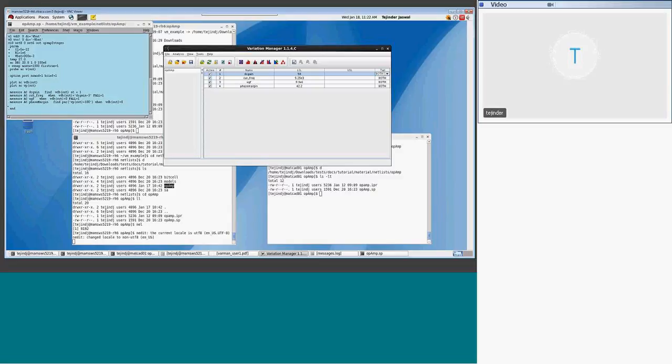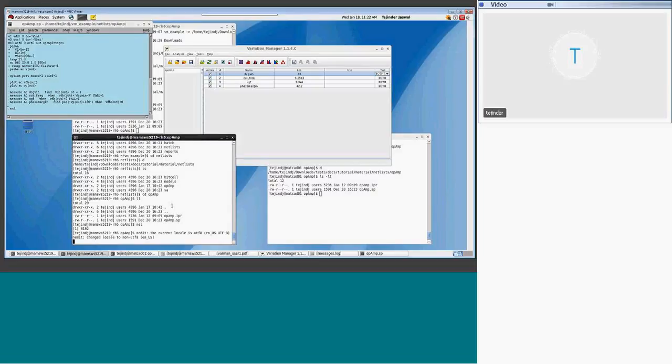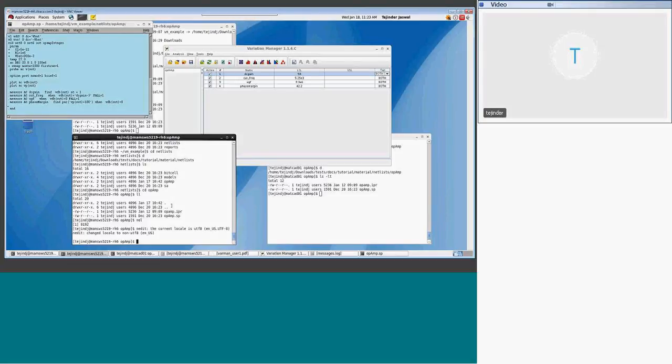So for LSL and USL, the lower and upper specification limits, you can define both. If, for example, you do fast Monte Carlo, you don't need them. If you know them, you indicate them, and the tool will check if any samples fall outside the limits. But it depends on the analyzers. In some situations, you don't need them.